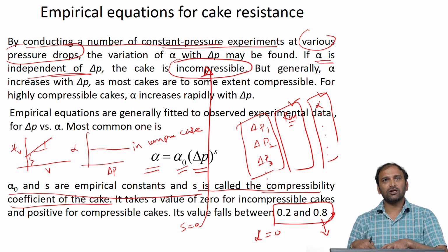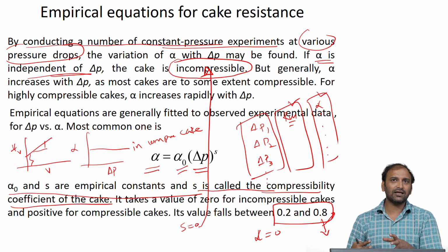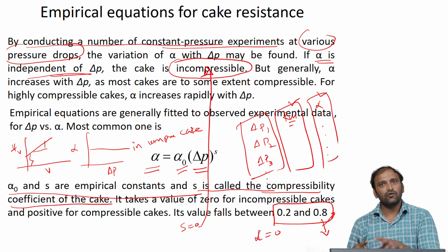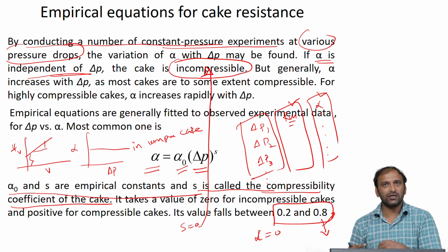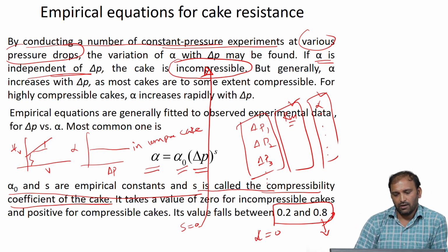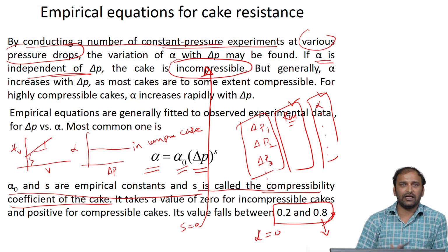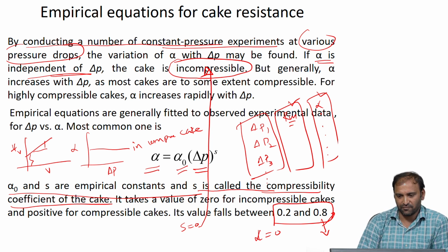Therefore, this particular framework gives you a way of calculating both the filter cake resistance and the filter medium resistance, which in turn can be used as a method for identifying the nature of the filter cake that is formed during the course of filtration.